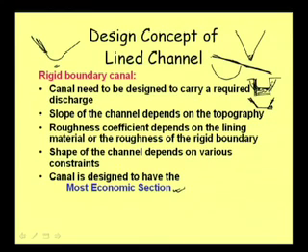So, our channel should be such that its cost is less, and this is the very basic concept we follow. The channel shape we get, we call that the most economic section, and that particular section is also called the hydraulically efficient section, or the best hydraulic section.